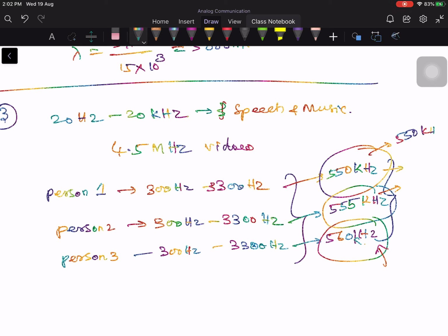So this also overcomes the difficulties of power radiation at low frequencies. See, it is like throwing one stone and getting two mangoes. The first is that you are avoiding the confusion or mixing up of this voice, and also you are talking in terms of 550 kilohertz, thereby you are reducing the antenna size also. That is one more advantage that you are getting.